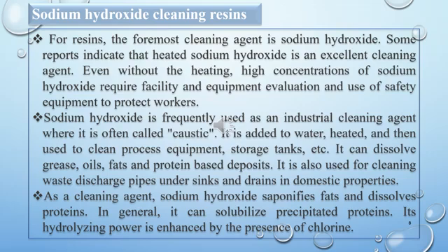The first point is, for resins, the foremost cleaning agent is sodium hydroxide. Some reports indicate that heated sodium hydroxide is an excellent cleaning agent, even without the heating. High concentration of sodium hydroxide requires facility and equipment evaluation and use of safety equipment to protect workers.